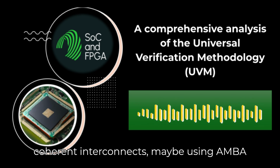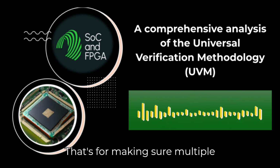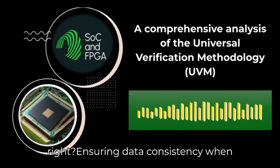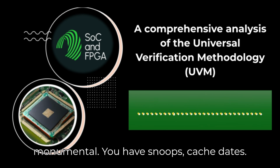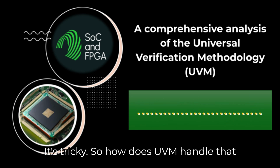Or consider cache-coherent interconnects, maybe using AMBA ACE, which is a common standard. That's for making sure multiple processors see the same view of memory. Right. Ensuring data consistency when multiple masters are accessing shared memory. The complexity there is monumental. You have snoops, cache states. It's tricky. So how does UVM handle that complexity?